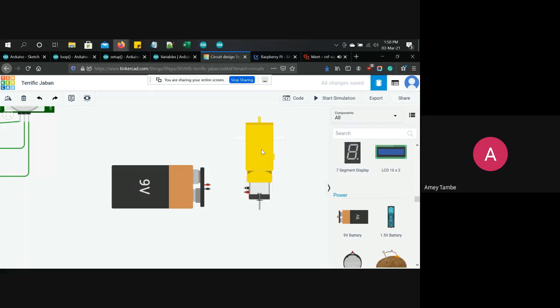The type of gear it has, and the assembly and mounting of that gear, define the rotation. Maybe it is a forward rotation, or it can be a backward rotation. If you connect positive to positive, negative to negative, it will move in a certain direction. If you want to reverse it, you need to swap the connections.